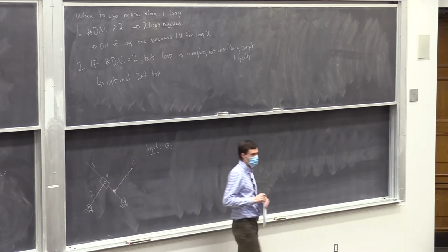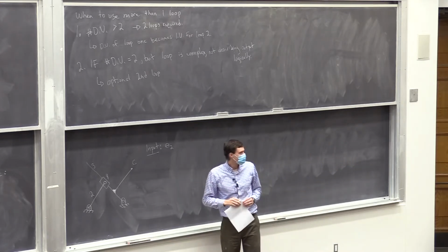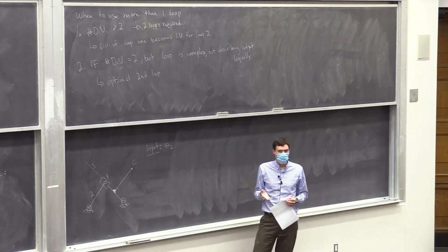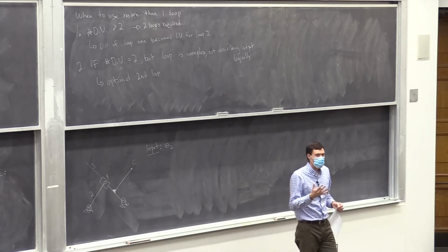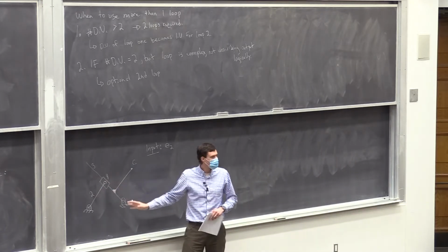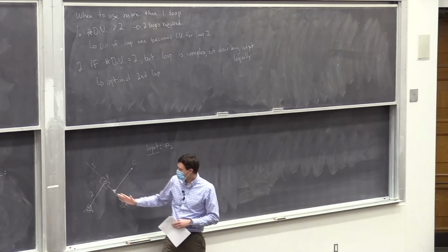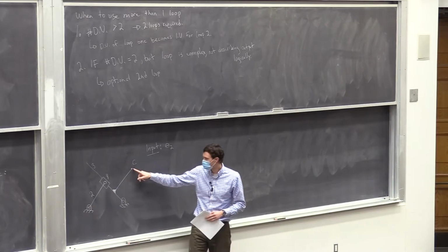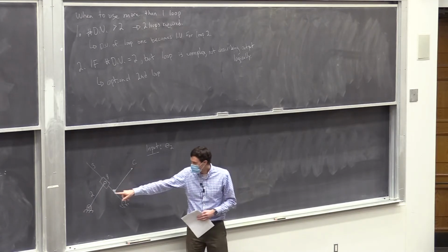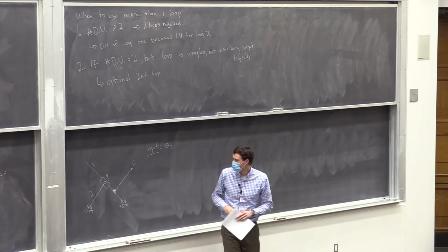And this is something that I've done a lot. I kind of spice up a mechanism by adding an extension. The reason I often do this is that it comes up really frequently in real machines that the base mechanism may be quite simple, but the output location isn't right along one of these lines. The output, or input maybe, is off on some extension, and it slightly modifies the behavior of the link.